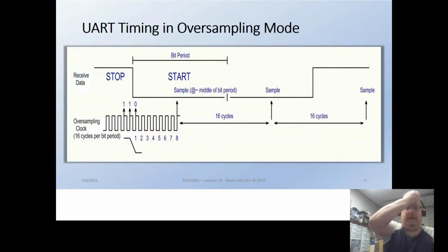Okay, well, the trick for finding this clock rate that they use. Now that you're trying to synchronize this clock, we've already figured out we want to synchronize the clock. Well, how are you actually going to do that? You're going to have to figure out a way to force the edge to be in an arbitrary starting spot. It's some analog thing that slows it down until it synchronizes, or speeds it up until it synchronizes, or it's a phase lock loop, or all kinds of strange mechanisms that you could do.